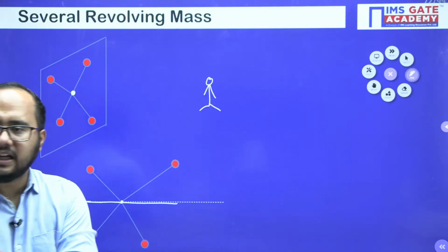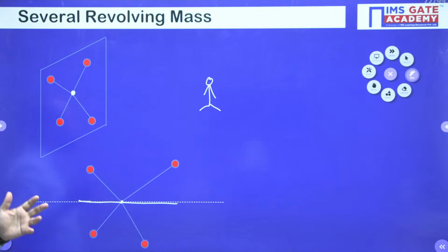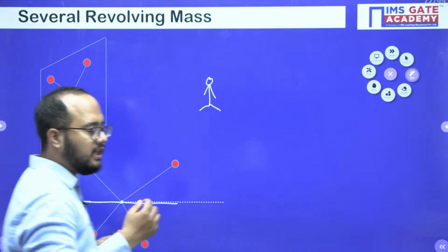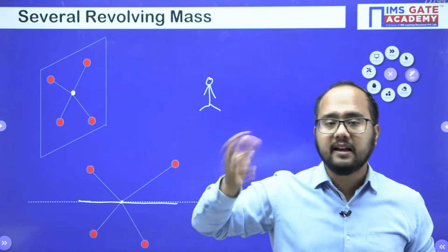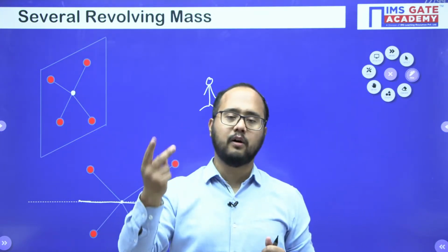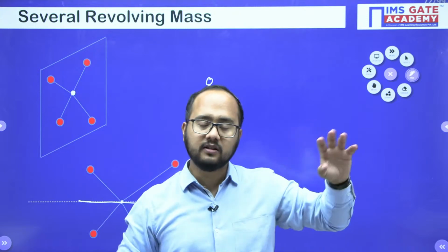Okay, I will tell you the approach here. Obviously it will be confusing, because you need to place the balancing mass to balance the whole system. Now, when I say balance the system, you need to consider two important things: the force and the moment.